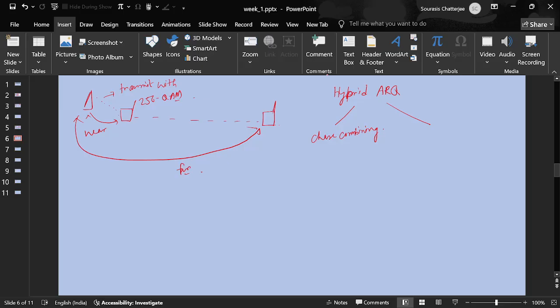So in chase combining, can one of you please tell me what the base station transmits? Does it transmit the parity bits or does it transmit the message bits? What does it exactly transmit? It will combine the error bits, and whenever it is able to decode successfully, it will send ACK. Okay, we'll get there. It's absolutely true that when the user is able to decode the information, it will send a positive acknowledgement. But I am interested in what happens in this chase combining protocol.